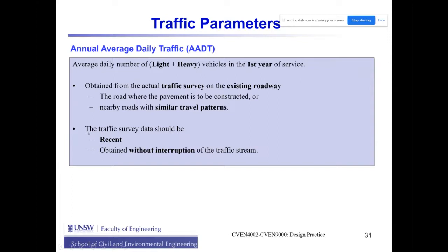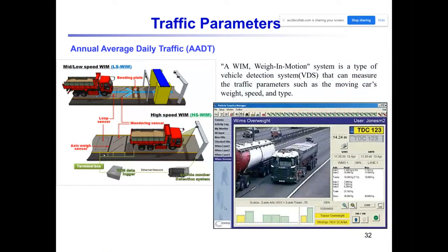Also, the traffic survey data that you use must be recent. You cannot use the results of 10 years ago. It should be recent, and also it should be obtained without any interruption. If there is any interruption, then it won't be reliable. The results cannot be used.